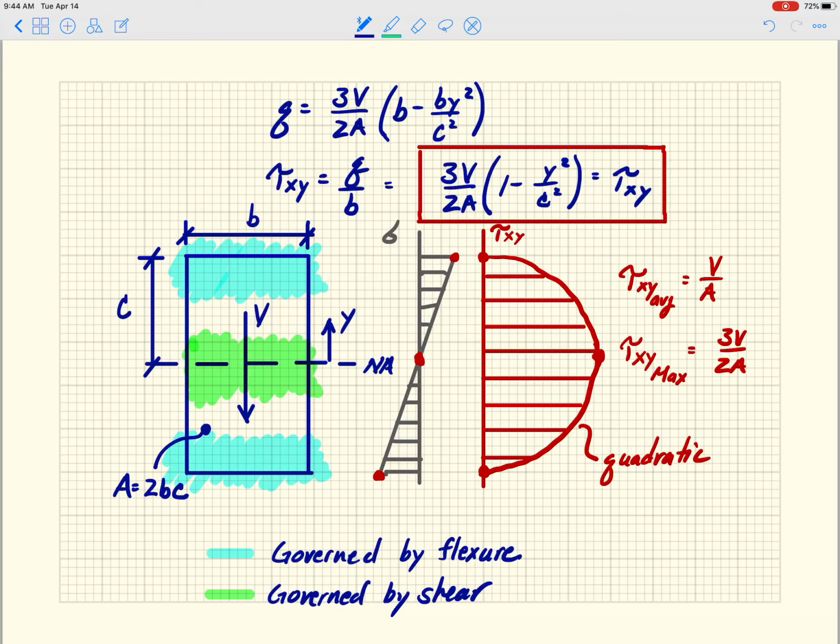Right? So you can start to look at a beam and see what demands that beam is actually being exposed to. And it's those demands that drive a lot of the shapes. So the web, that vertical middle piece within an I girder, primarily takes shear. Whereas the flanges, those horizontal elements pushed as far away from the neutral axis as we possibly can, primarily take bending. And that's an assumption that is used quite often in design.